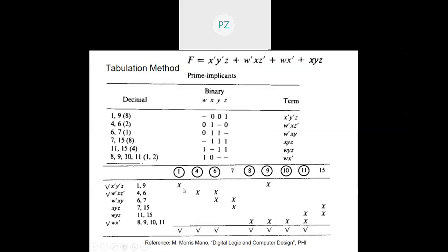In the last step, when you are writing, don't write the don't care conditions here. Just write the min terms or the max terms here and try identifying the essential primes. For example, if there is a don't care which is covered by any one, that will not be an essential prime implicant now, because that is covering a don't care and not one of the main terms. So the only difference when you involve the don't care is in the last step, do not write the don't care beyond this.